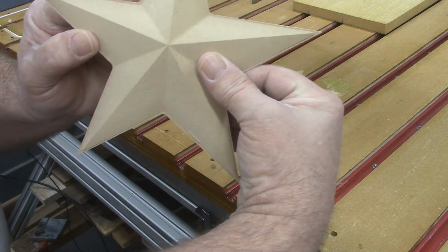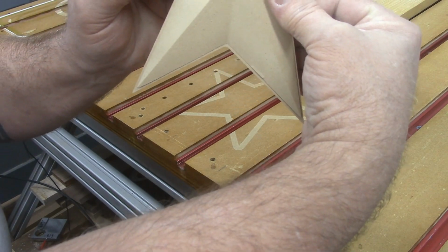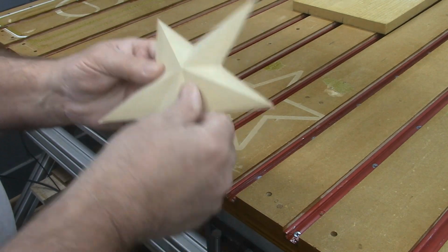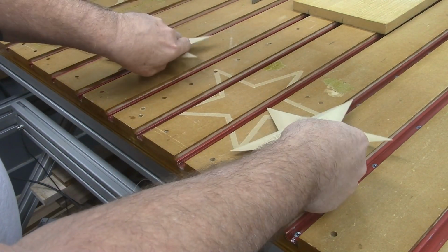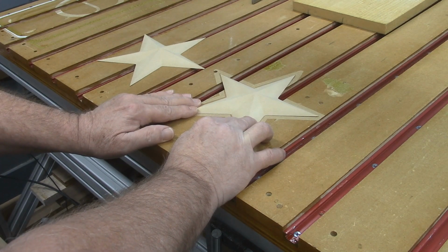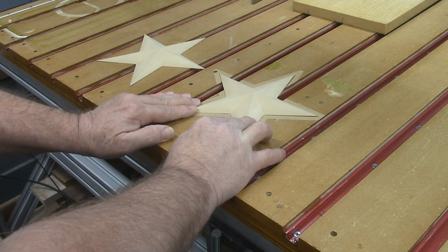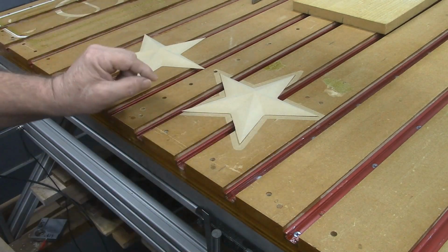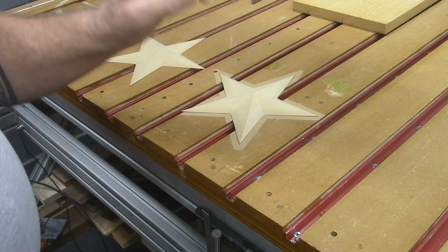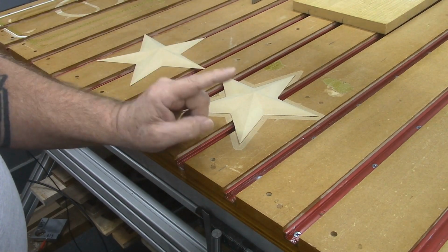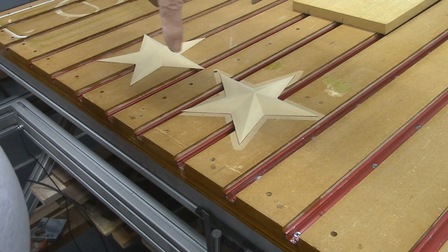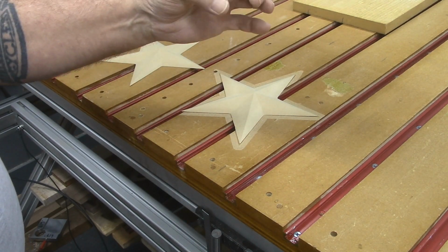They're just a little bit different. Well, why is that? Well, it simply comes down to the radius on that tapered ball nose bit. The software calculates where that bit is going to carve based on the cutting surface of that tapered ball nose bit, not the bit's total cutting diameter.